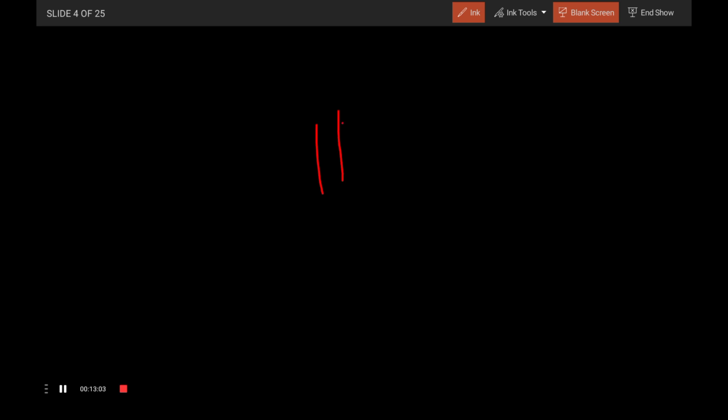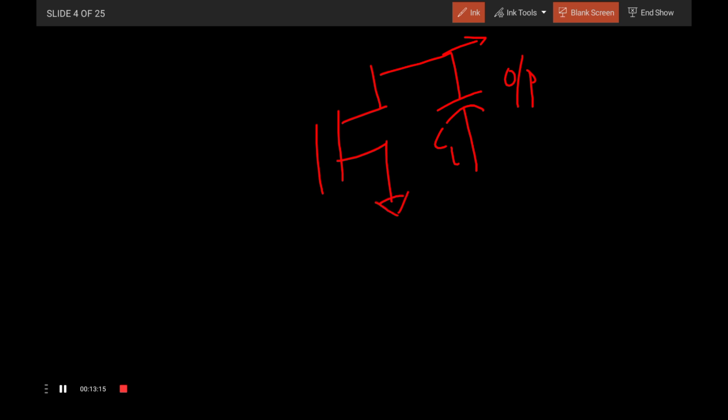Suppose you take one nMOS transistor. On the output side you have one capacitor. So this is the output section. This capacitor I will call CL, the load capacitor, and it is connected to the ground. This is the case for logic 1. Initially the capacitor may be charged to a higher value. Let it be considered that it is 5 volts charged in the corresponding capacitor.